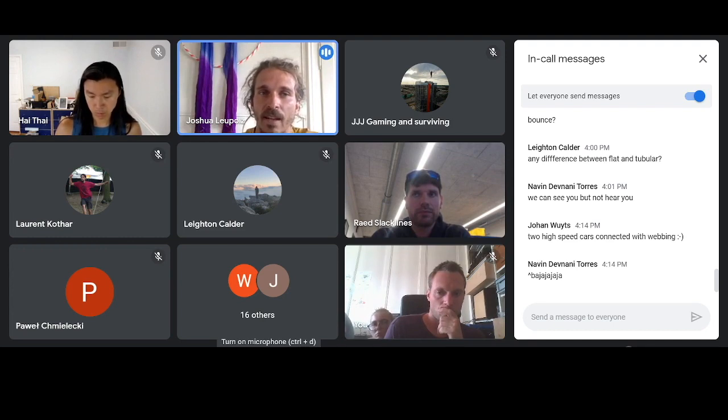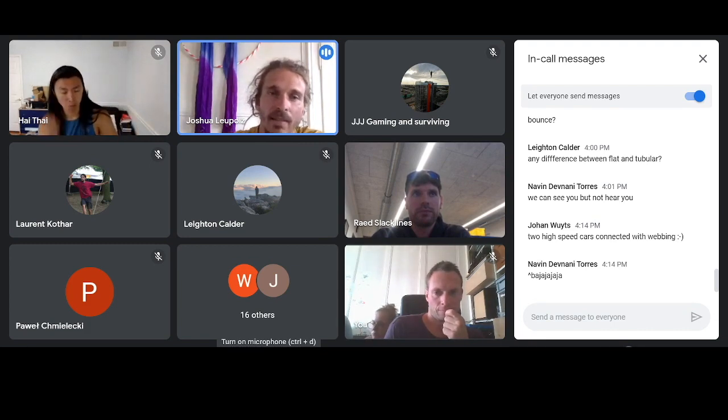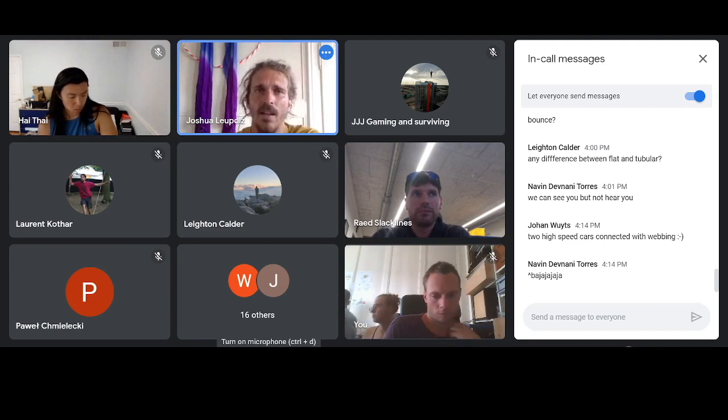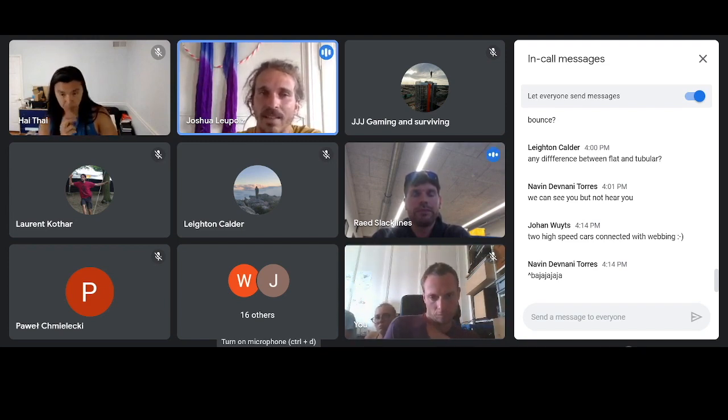And then you basically have a guideline in which range it needs to be. So we can define, okay, it needs to be between 2 and 3 hertz, and then you need to be good enough to actually hit this exactly. And if you're out of this range, you just need to repeat the test until you are within this range, and then you can do the tests. And then there's the question, how precisely do you always get up to the 5 kilonewton? That can be a bit more tricky.